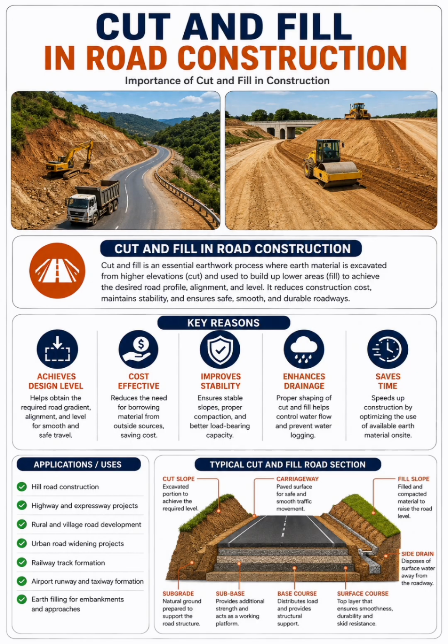So cut and fill actually helps to reduce the need for borrowing material from outside sources, saving costs. So instead of going out to get your material from other places, since you already have the material that you cut from a particular high elevation, what you just need to do is to test the material to see if it meets the standard that you need, if it's going to actually carry the load that is coming upon it. If the material is satisfactory, you can make use of it, thereby saving the cost of going to buy or borrow material from other sites, right? So this is for the cost effectiveness of cut and fill.